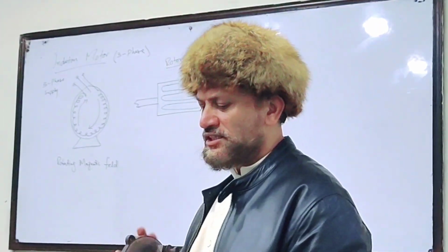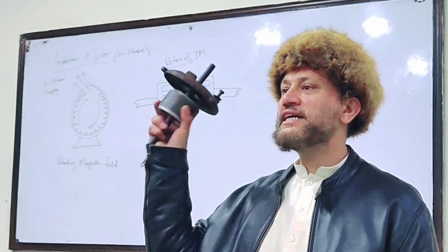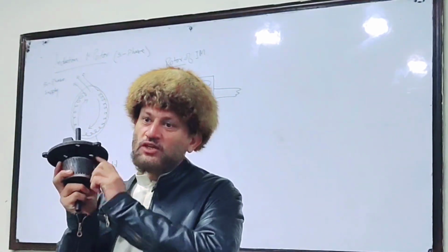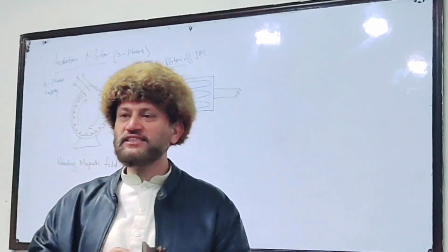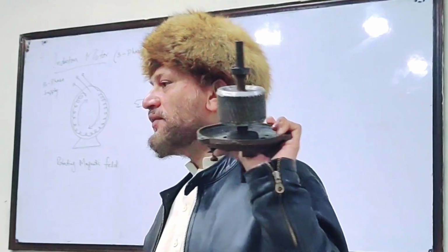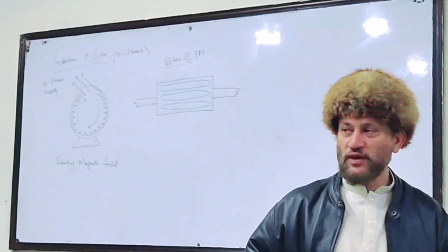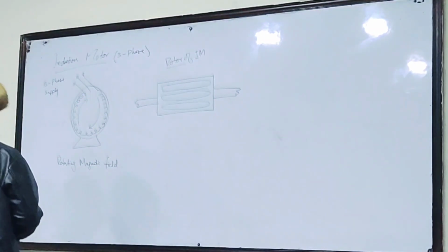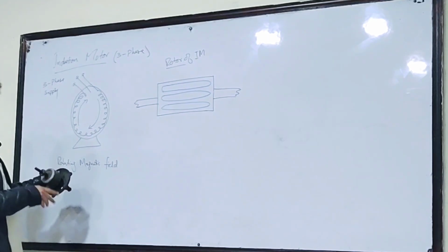Understand my point. But for you guys, in these lines there are copper bars inside. Understand? वायर से कोई कनेक्शन इसमें नहीं होता है. इसके अंदर जो है ना कॉपर बार्स होते हैं, वो शॉर्ट सर्किटेड होते हैं, and then it is packed with that. Understand my point? Now what will happen when I place this rotor inside this stator, like this?